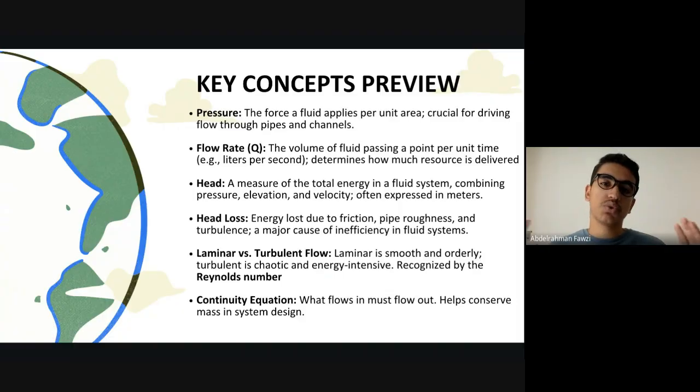You want to make sure that inside this pipe, the internal pressure is lower than the pressure that you are applying. The internal pressure means the vapor pressure. If the vapor pressure is higher, then this fluid is going to vaporize if it is a liquid. And if it is a gas, it might explode. So you need to make sure to understand the pressure issues.